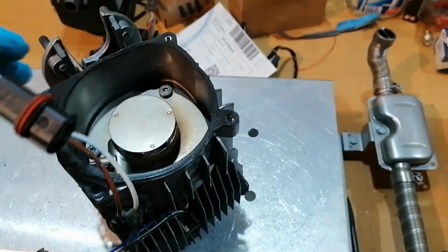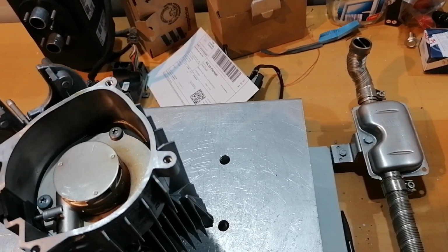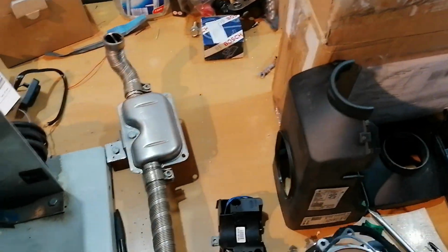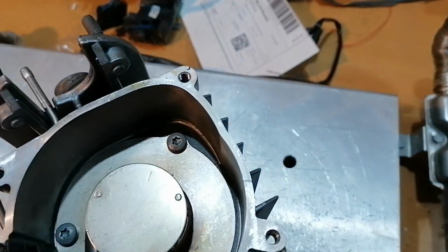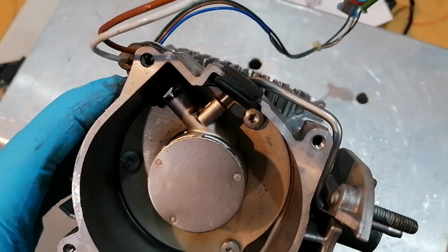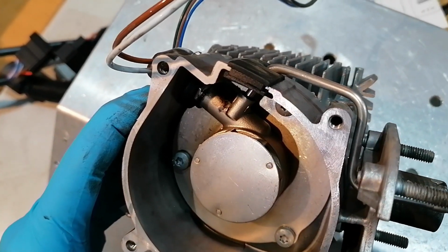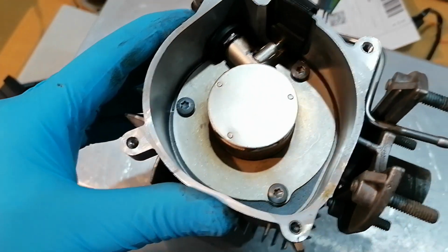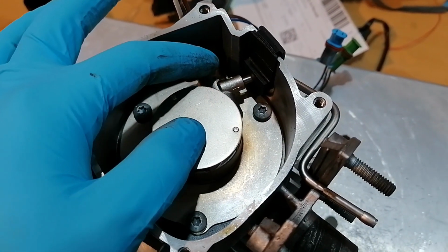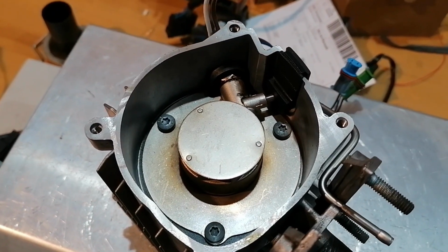Okay, we have a gasket that is mounted here, and we can already see there is some unburned fuel here. Taking a look inside, I think some holes are filled with dust from the burning chamber, and also there's a strainer inside here, and I believe we need to change that.